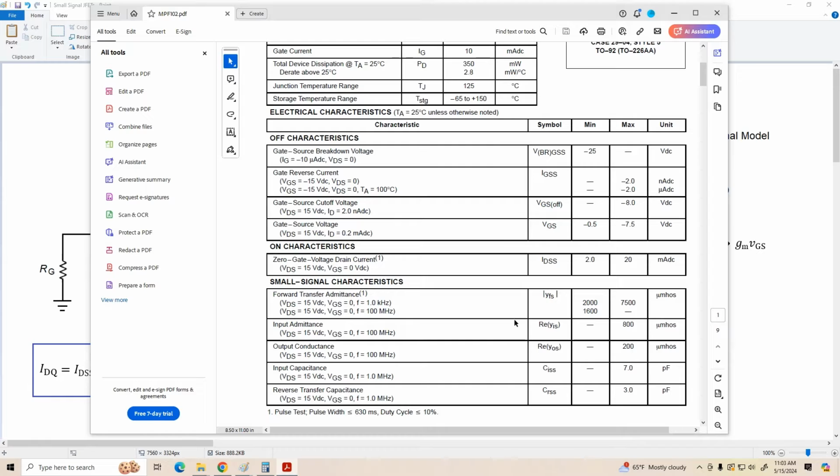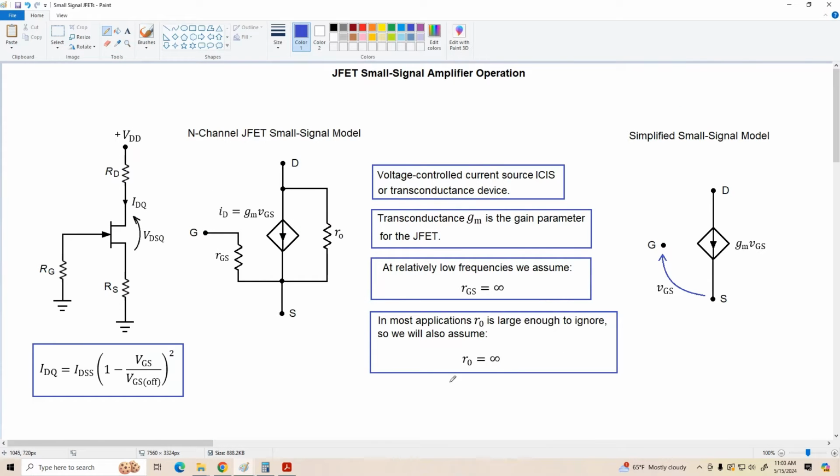But one of the things you'll find out eventually is that FETs have a lot in common with vacuum tubes, and we're going to see a lot of this terminology used there in the future as well. But anyway, I wanted to use this as a segue to introduce the notation here, and that is we're going to measure or specify transconductance in the units of mhos, which is represented with an upside down omega.